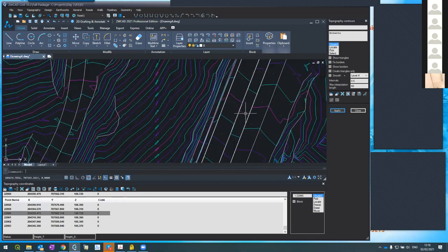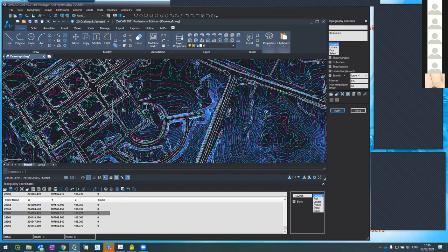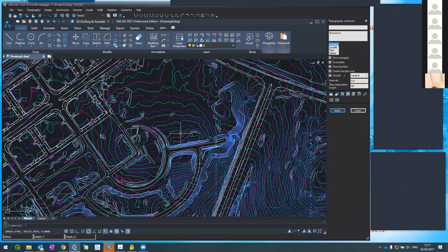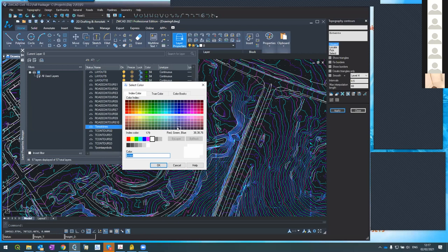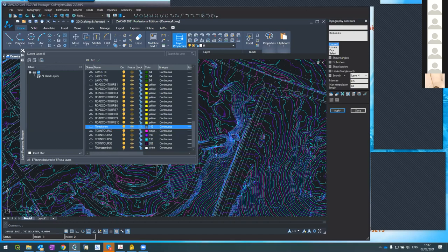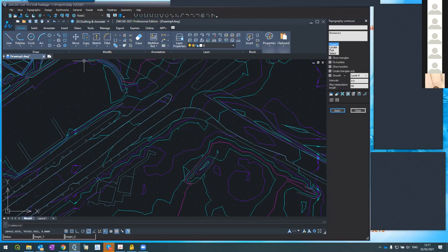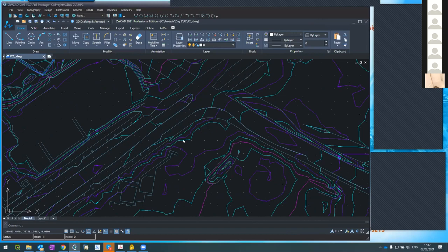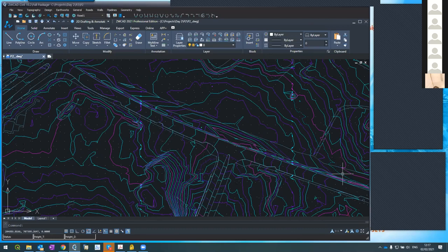You see this is our existing road. You can see the camber. These are existing roads. Okay, what I'll do next, I'll take the break lines, where is it, the break lines, and convert it into something that will be on the background. Okay, yeah, now it's easier for me. Good. So I prepared the surface. And now what I'm going to do, I'm going to design a horizontal alignment here on this road.